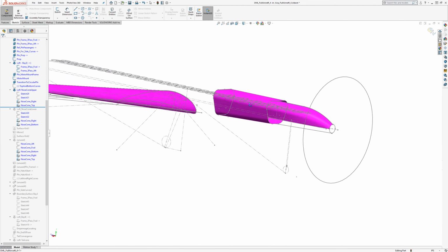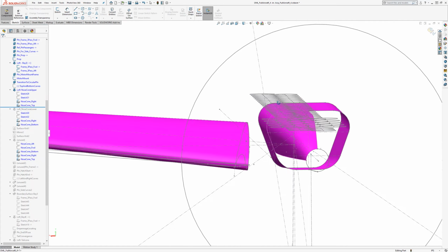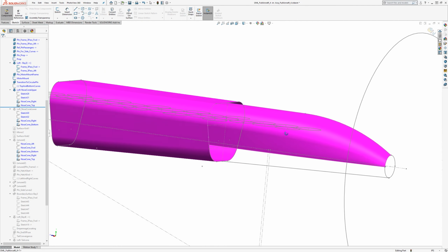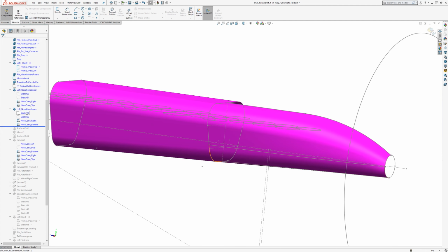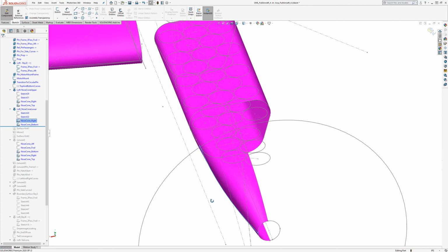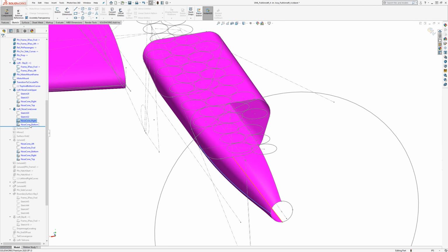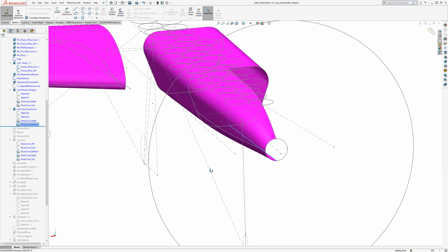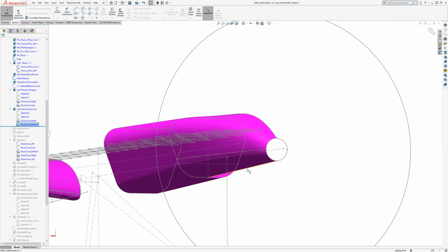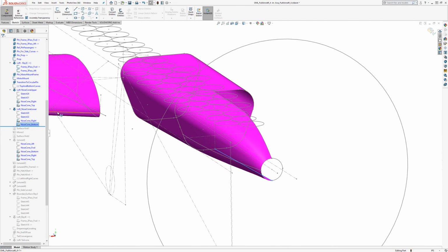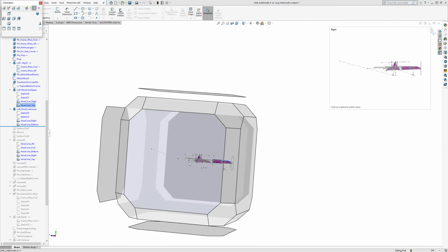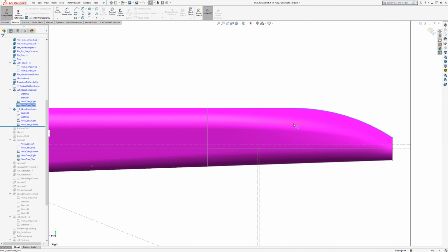So then for the nose cone, this has a lot of curvature in it, so I did it in two parts and then mirrored it. That's pretty typical. The bottom is coming from the bottom curves sketch, and then a right, and also a top that makes sure it clears the last passenger that's going to be there.